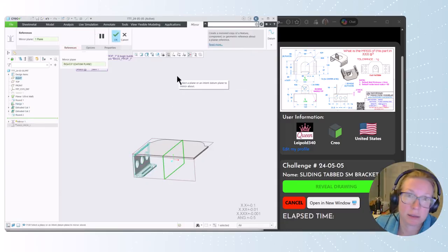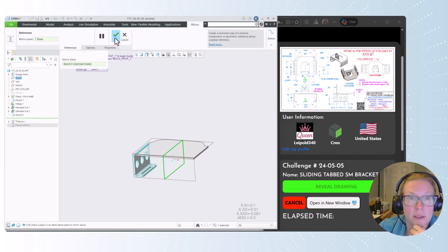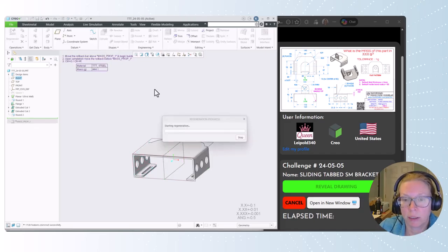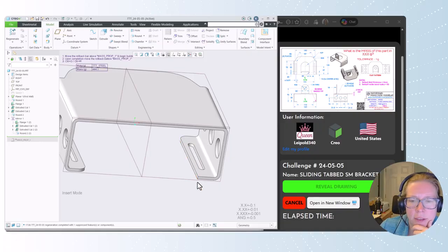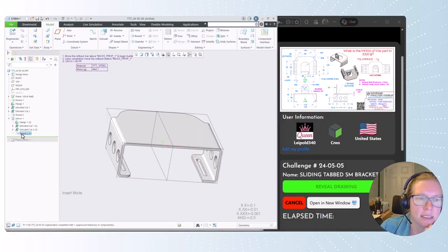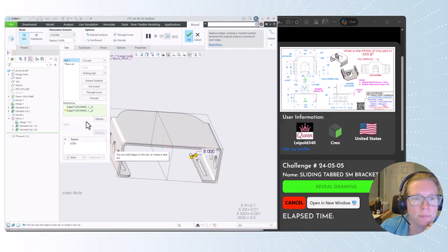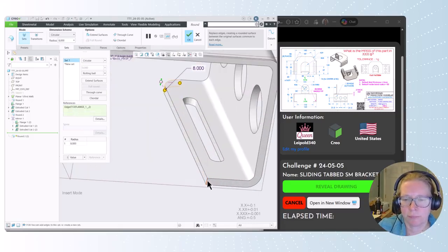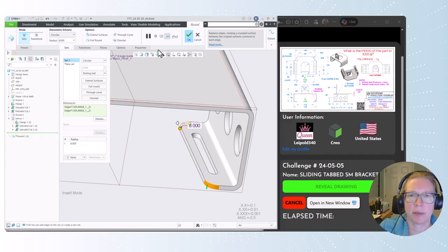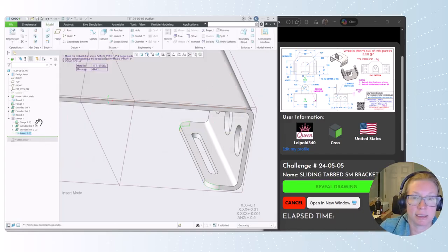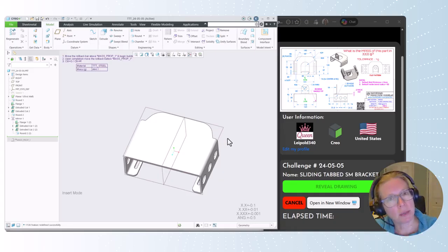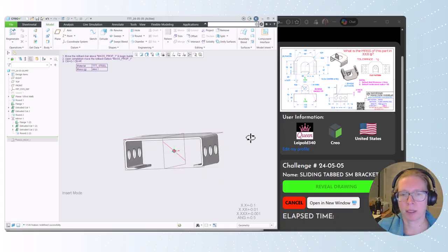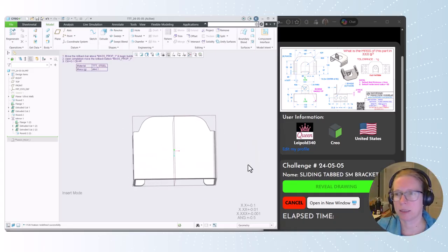Now this is the way that Creo used to work, that you didn't get the preview. Now they have the preview, but we don't have it here. So everything comes over. I noticed that my round 2 did not update. So let's edit definition on the round 2. Not sure what's going on there, but we can just go in and add that back in, and it keeps living under the mirror, allows us to fix it even though it probably should have worked, didn't work. Go ahead and just update that.